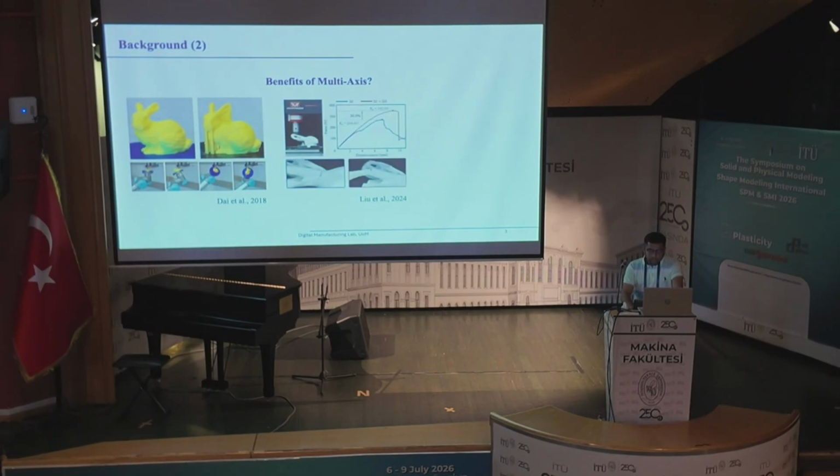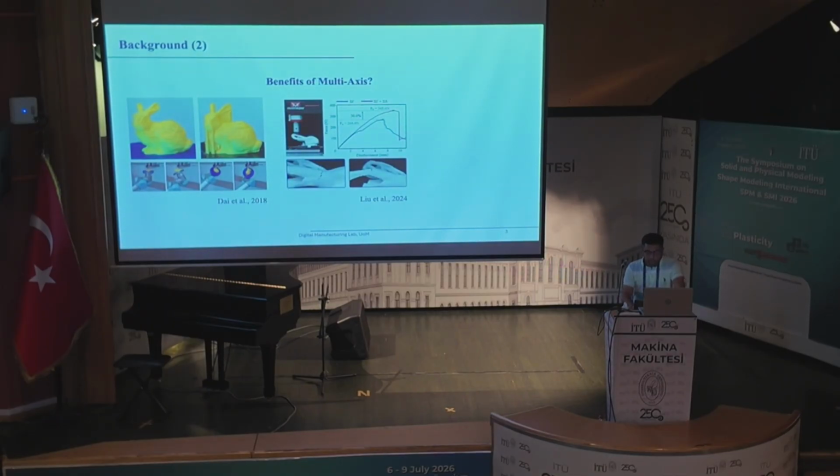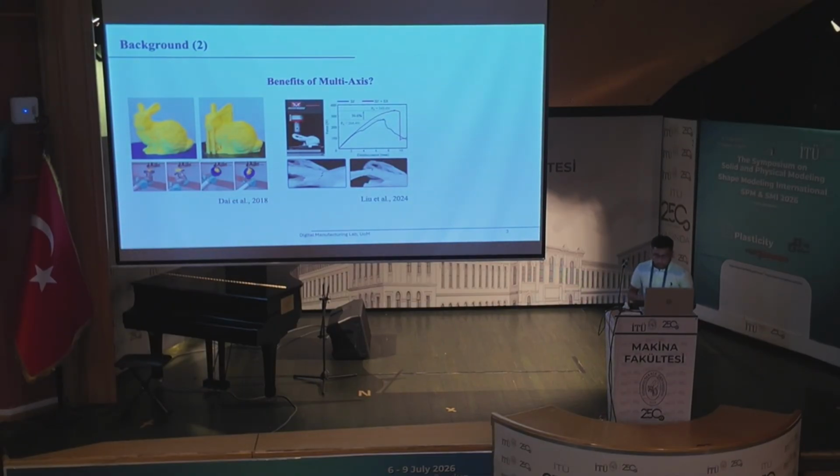But very recently, there have been more functional improvements in the application. This paper showed that we can increase the strength of the parts by moving into higher axis of motion, because we no longer need to be in a planar domain, so we can deposit material in a curved way.